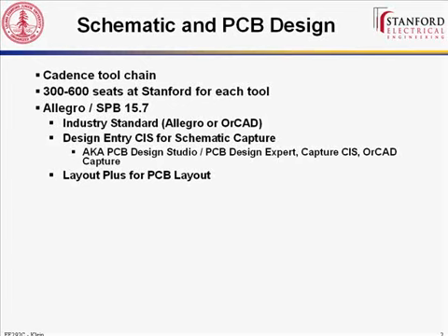So we're going to be using Design Entry CIS for our schematic capture. That's the name of the program you're going to launch. There's a whole lot of programs that will install, including Design Entry HDL, which we're not using. So make sure you run Design Entry CIS. This exact same program for schematic capture, from what I can tell, it's even the same executable file, is also called PCB Design Studio or PCB Design Expert as part of the Allegro tool set.